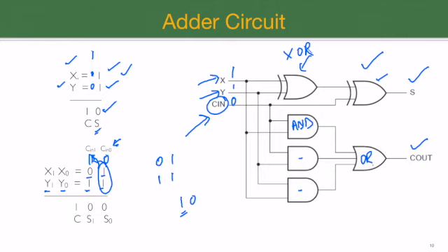So here exclusive OR of 1 and 1 is being produced. Exclusive OR circuit wants only one of the values to be 1, and then the result will be 1. If more than 1 bits are 1 or all of them are 0, then exclusive OR produces a value of 0. So we will get a 0 as output here, which is becoming input for the next exclusive OR gate. Then this carry bit value of 0 is being forwarded here. And 0 and 0's exclusive OR also produces the result of 0, which is what we have seen over here.